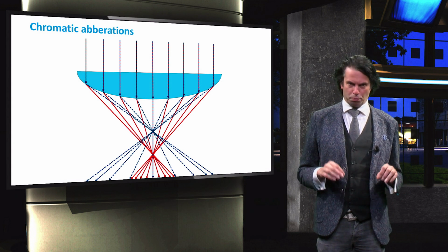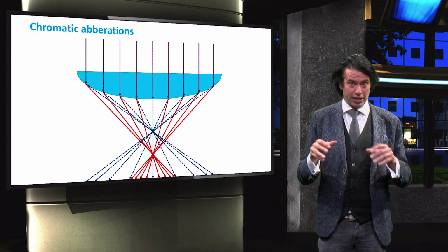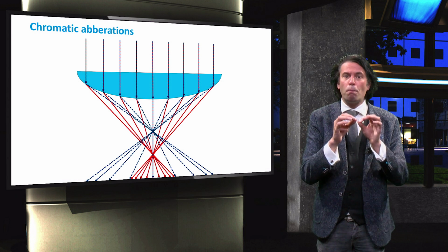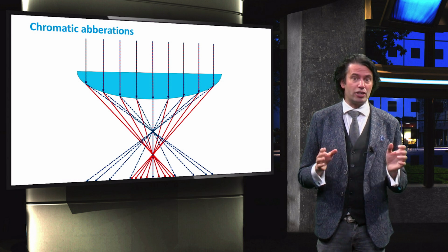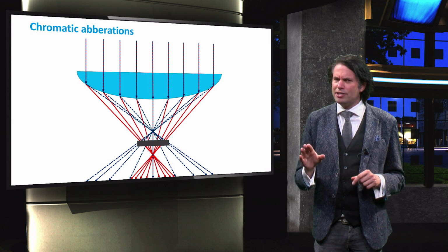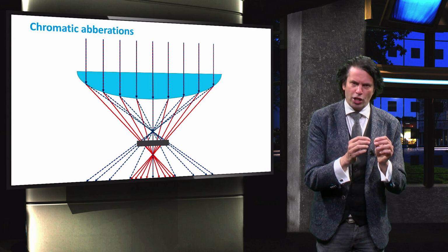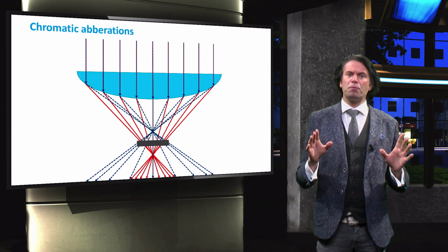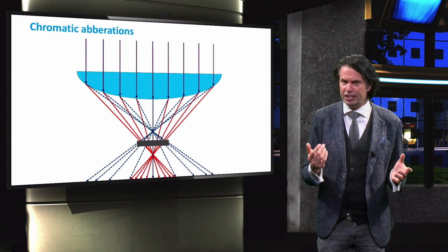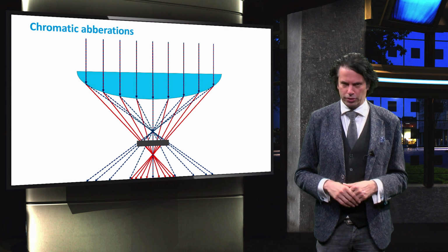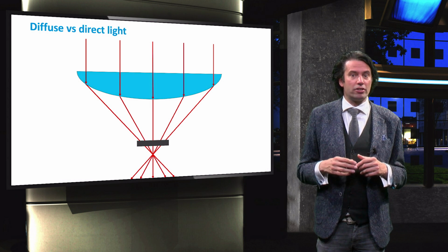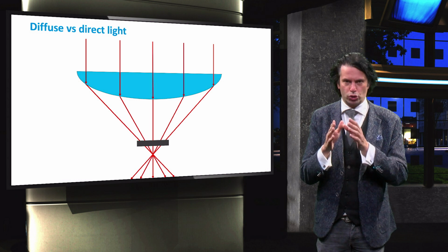These optical aberrations pose some serious challenges for lenses in imaging devices, such as cameras and beamers, where a concentrated focal point is essential for creating a sharp image. For concentrator PV, the light needs to be focused onto a solar cell with a certain area. Even though the optical aberrations have to be considered during the lens design, the lenses used for CPV have a much larger tolerance. This lens is designed such that all perpendicularly incident light is focused onto a solar cell.